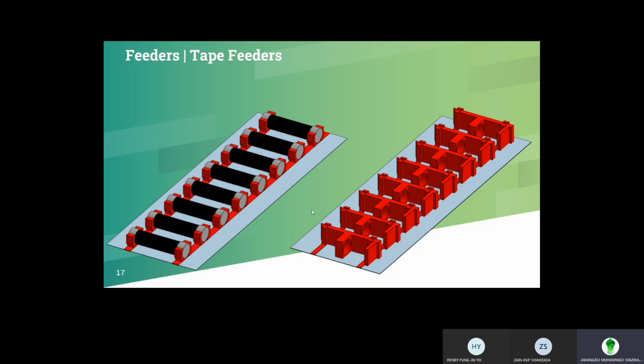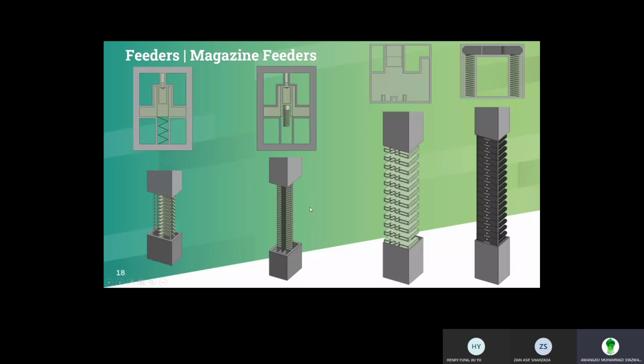For magazine feeders, we are feeding the 2 variants of the safety caps, the pin isolator and the LED module. We are utilizing the magazine feeders for this due to their stackability attributes, where most of the surface on each side has a considerable amount of surface contact, as we can see here.